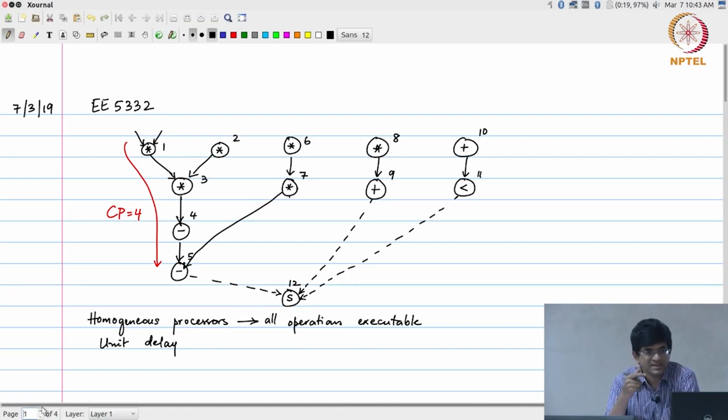Okay. This is something you can actually observe when you use Vivado HLS for synthesis. As you change the timing constraint, you will find that the hardware resource usage increases, and the type of pipelining that it does changes. It basically tries to chain operations into a single clock cycle when possible, and if it can't, then it will schedule them across multiple cycles, use up more hardware, more clock cycles, but still try and give you a correct result.